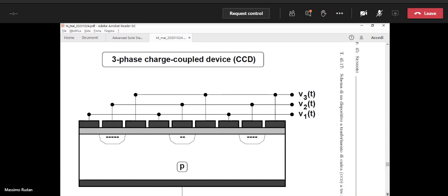Okay, so essentially, at the end of the integration period, we have packets of electrons that have formed under the gates in which a high value of the phase is applied. Qualitatively, you may understand these packets of electrons as associated to the amount of illumination that has come in those locations of the device during the integration time. Okay, so we have captured somewhat the illumination locally.